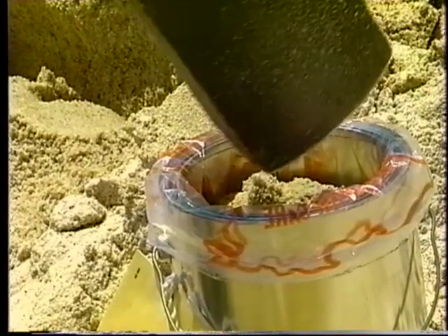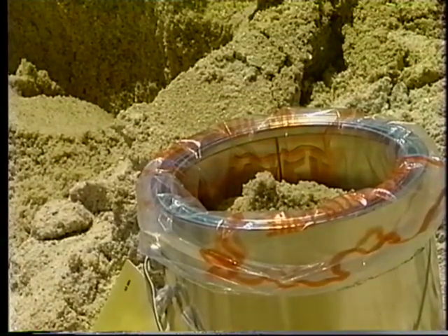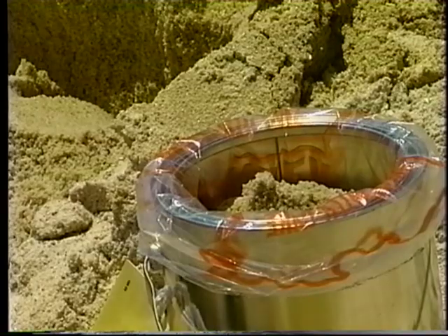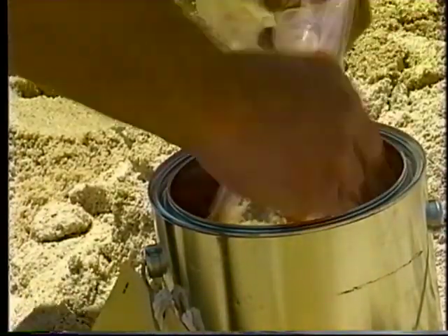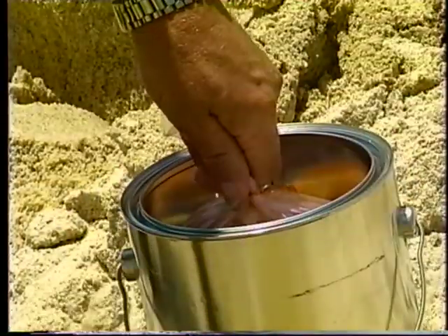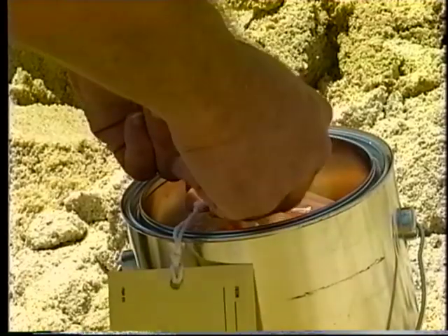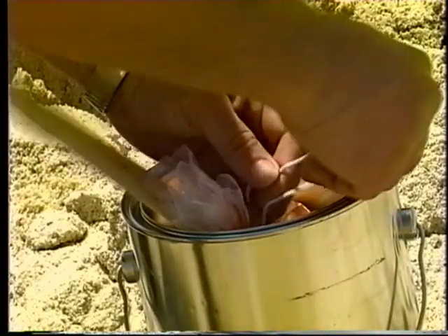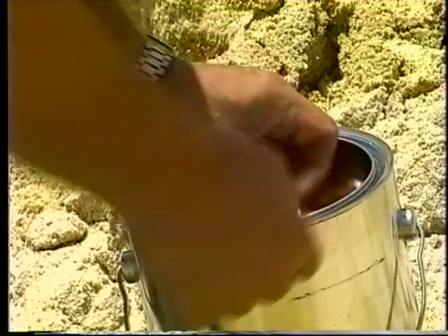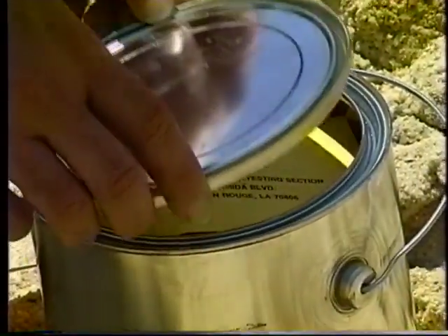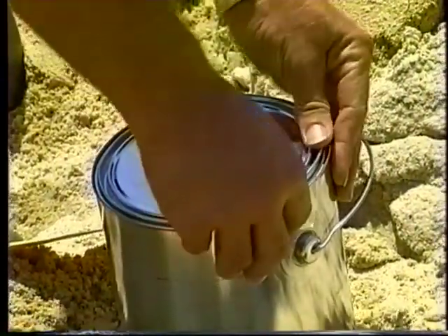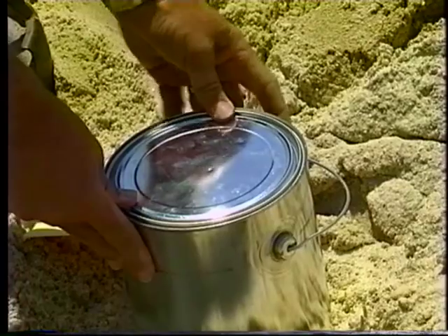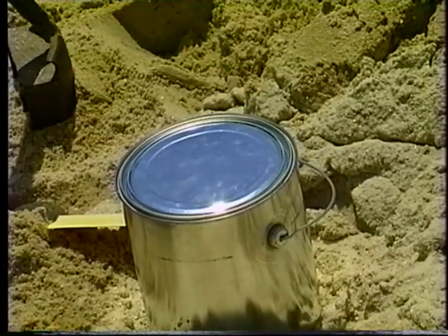If moisture content is to be determined, the sample must be protected from moisture loss. When you take a sample for moisture content testing, seal it in a clean, dry, friction top can large enough to hold the needed quantity and cover it immediately. This will prevent moisture loss. If you are sampling soils, place the sample in a plastic bag first. Then, put the sealed bag into the friction top can. Remember to close the can immediately. Failure to seal the can will allow moisture to escape, resulting in an invalid moisture content value for the material.